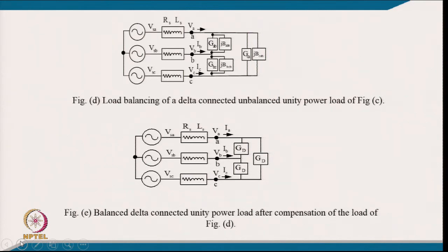So now we can put another set of compensator here, typically for providing the balancing. I mean balancing in the sense of what Siemens has given, that even a single phase load can be realized as a balanced load. Any unbalanced resistive load, these three unbalanced resistive loads, by putting a compensator, this three phase load can be realized on this system as a balanced load and resistive load.